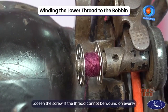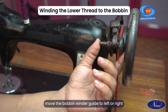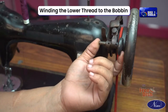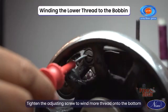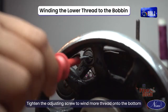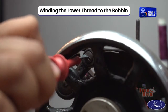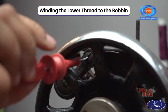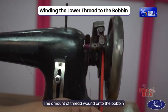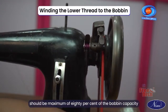Loosen the screw. If the thread cannot be wound on evenly, move the bobbin winder guide to left or right. Tighten the adjusting screw to wind more thread onto the bottom. The amount of thread wound onto the bobbin should be a maximum of 80% of the bobbin capacity.